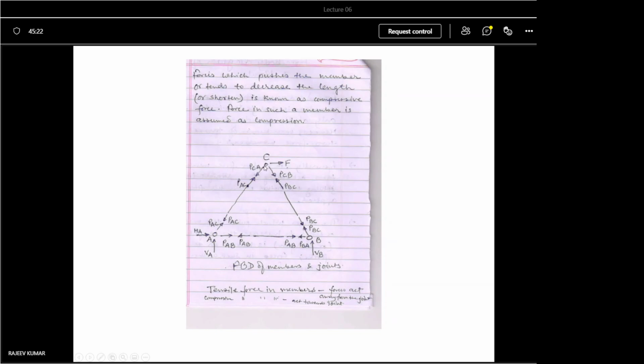Here the structure is there, the reaction surface, the ground, or a pillar, or a roller, but I am not showing it. That is replaced by only a force, the reaction force PB. This is the free body diagram. Here the hinge is there, and I am not showing it. I am showing only the forces VA and HA.